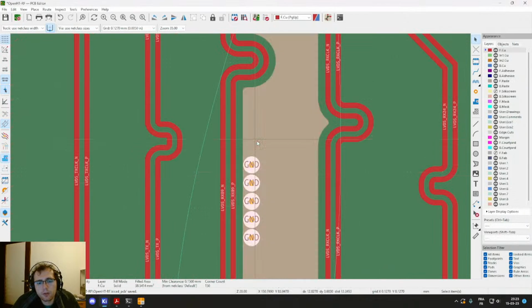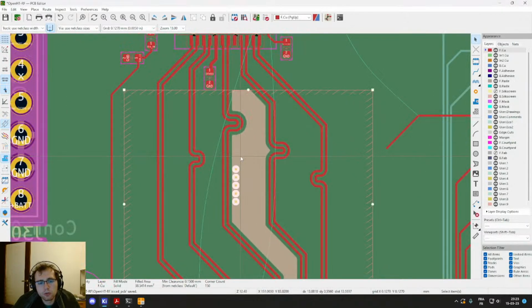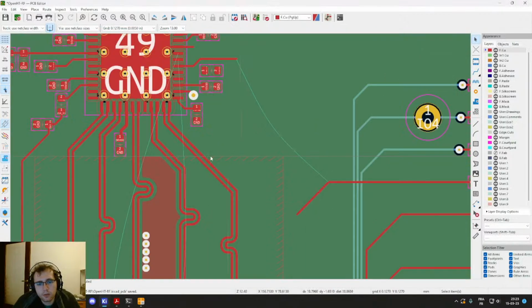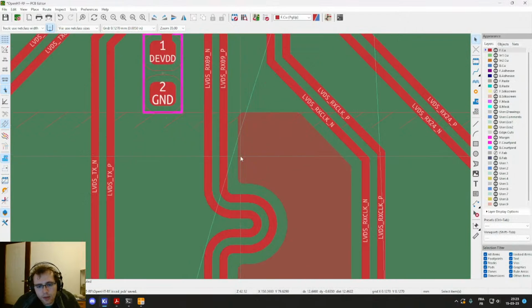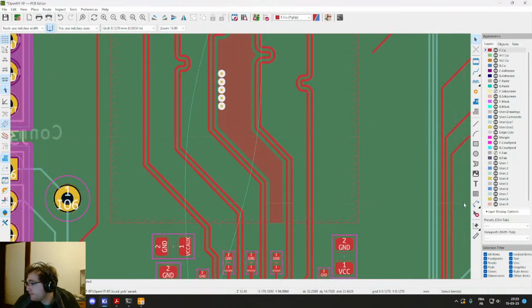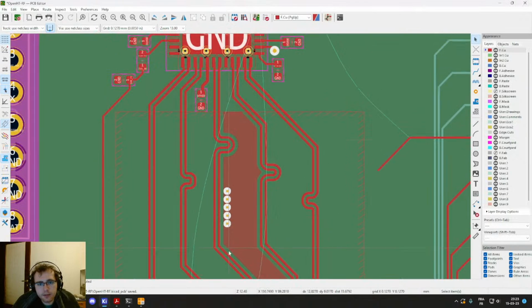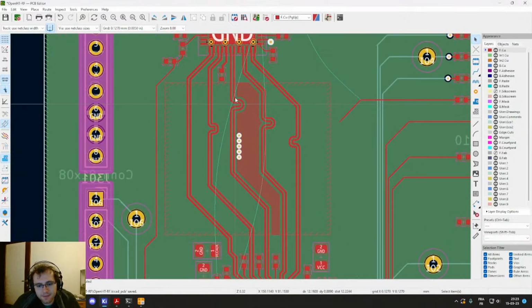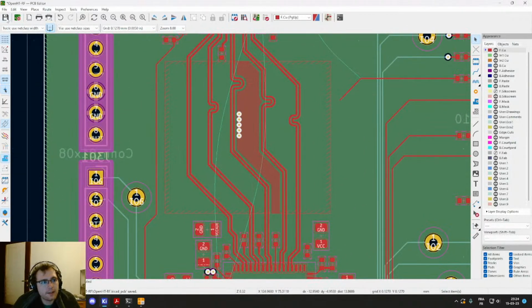So what we could also do is just not put any ground near the LVDS pairs and only rely on the ground below it, which is what it's designed to do. But yeah, doing it like this won't hurt. Okay, I hope you could understand me in this theoretical rant. I'm gonna save that. I'm gonna delete this actually. We are not gonna put the grounds now.